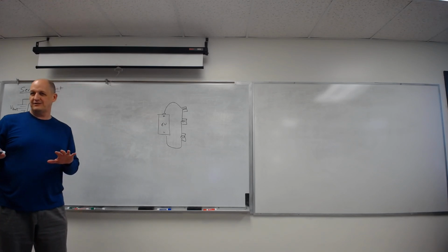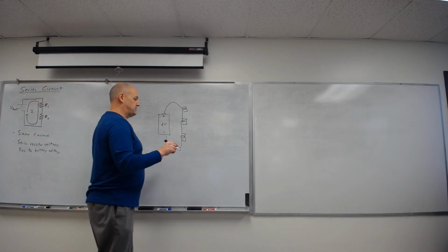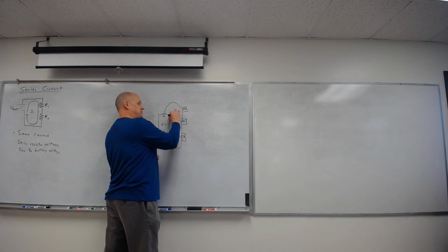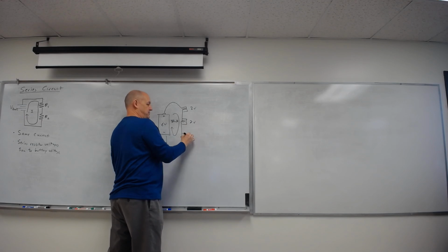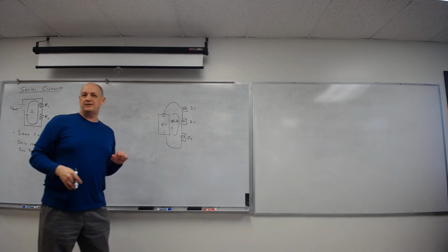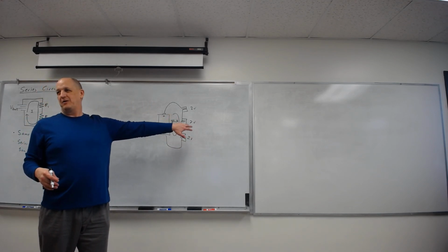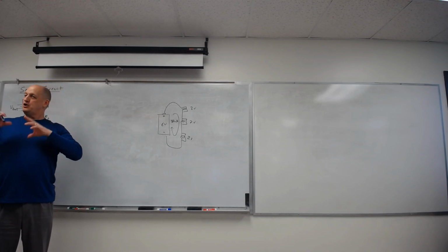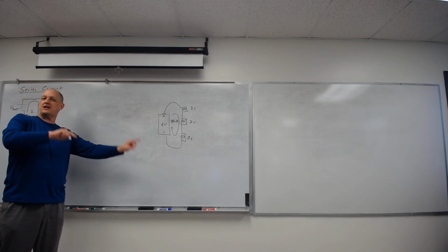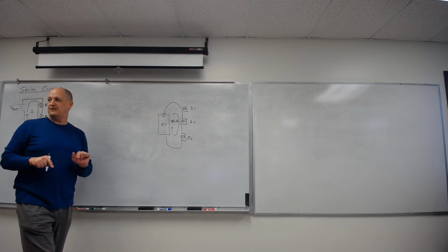So that's familiar. It depends on your specific light bulbs and battery and all. But they all should have been about the same. They're all about 80 milliamps. And each of these was probably about 2 volts. Your light bulbs vary a bit. Sometimes you get one that's way down close to about 1, up to about 3. Most of them should all have added up to 6 volts. You should have seen that. If you did lab 2 correctly for the series circuit, that's what you saw.